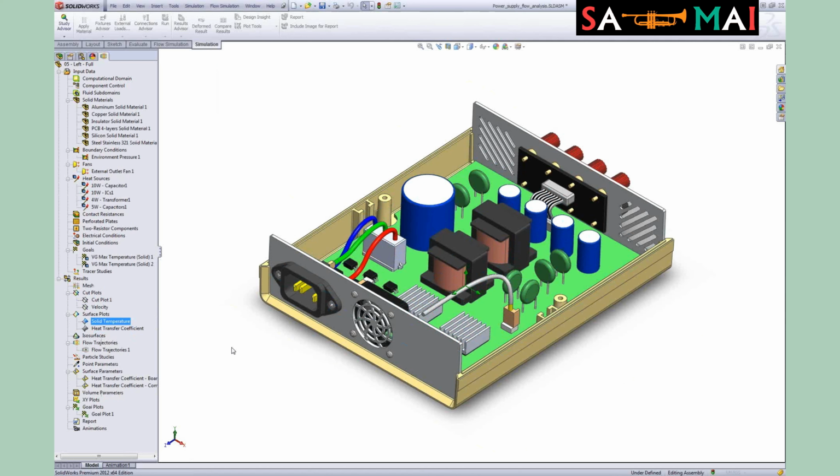And what you're going to see with this, with the full model regarding the solid temperature, is that the left fan looked very good from our initial results. But what we're going to see here is actually that we go above 100 degrees C because of the additional components that are blocking the flow from those heat exchanger fins. So at the end of the day, you always run the full model just to verify the results, and what we saw from this one was the middle is actually the best one to run.